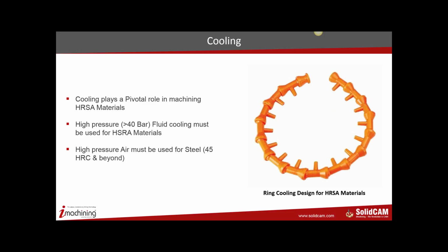If that is the kind of cooling that you're going to use, so if I make a drawing of that, this is my tool, and the coolant from this pipe up here falls like this. Okay? If this is how you're going to provide the cooling, I will recommend you not to attempt to cut superalloys, because this tool will not even last the very first contact with the material.